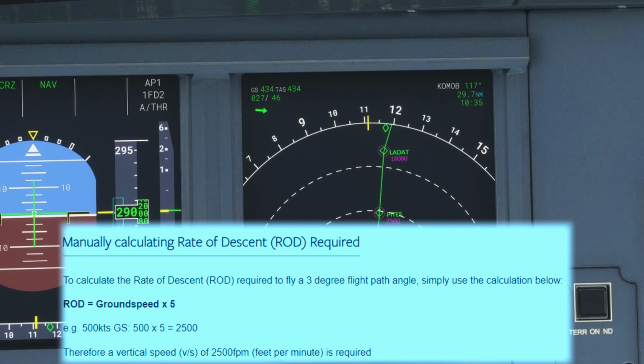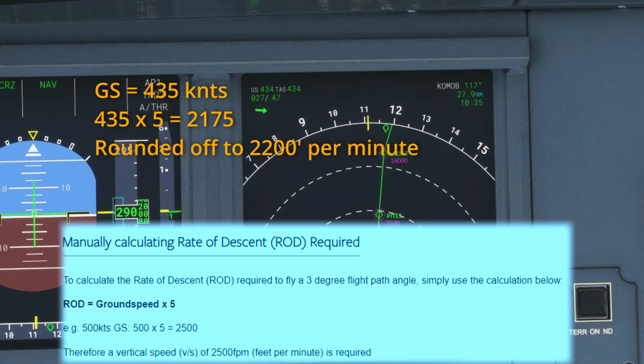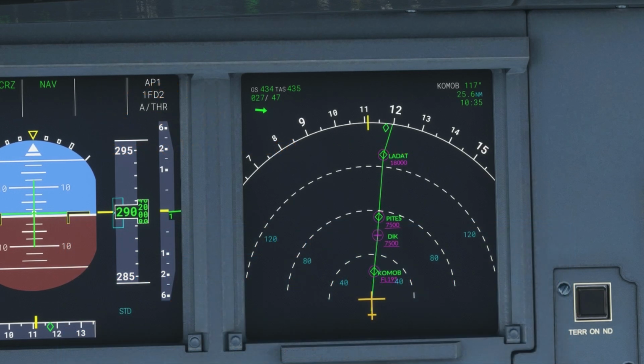To calculate a 3-degree glide slope, we can use the following rough guide. Take your ground speed, note it is your ground speed and not your true airspeed, and multiply by 5. So in our instance, we can see that our ground speed on the secondary display is 435 knots. Times this by 5 and I get 2,175. So I could plan on a descent rate of 2,200 feet. These calculations are not exact, but they're a fair rule of thumb, and certainly better than nothing.